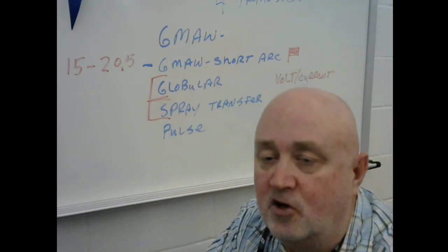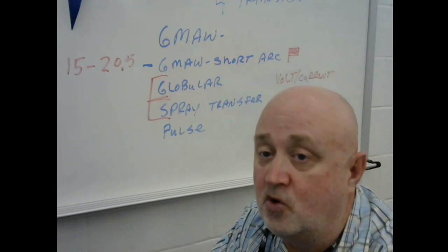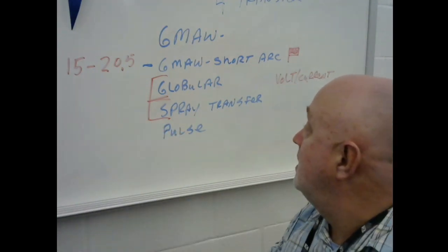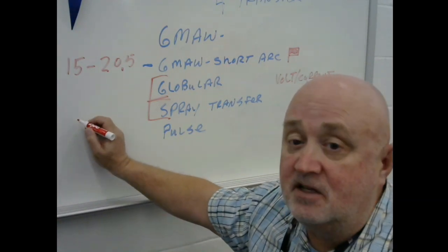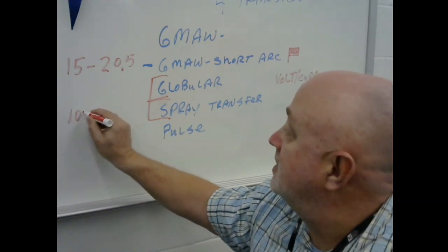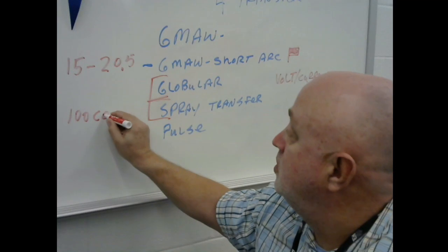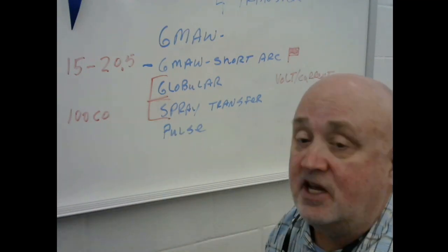Another factor that goes into play here with short arc or with spray: you can't get into spray with 100% CO2. It's not going to get there. CO2 will not get you spray transfer.